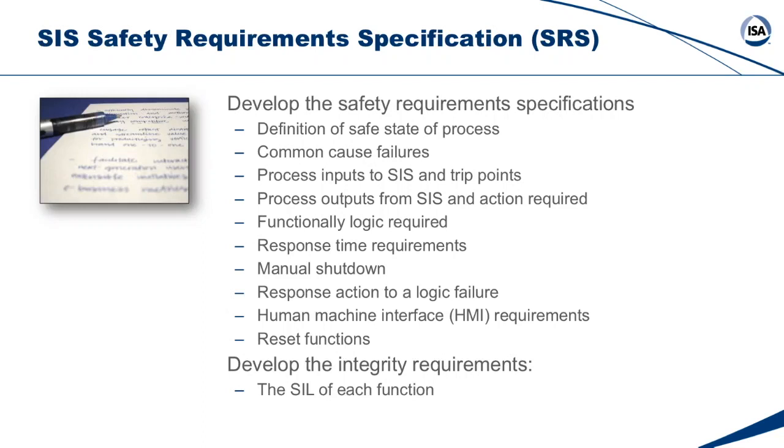You have to document the safety integrity level of each safety instrumented function, and certainly end users are concerned about reliability or spurious trips and unnecessary shutdowns. And it is in your best interest to specify what you want as a no more nuisance trips than X, or 10-year minimum time between nuisance trips on average according to a calculation. Because I can have the world's safest system and it can give you a nuisance trip once a week, meeting very, very high risk reduction factors. I can do that at the expense of lousy nuisance trip performance. So you probably want to specify both.